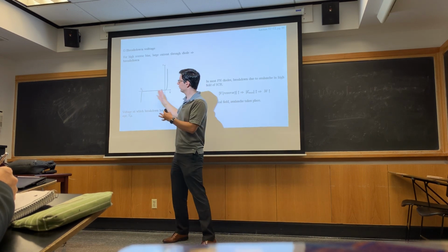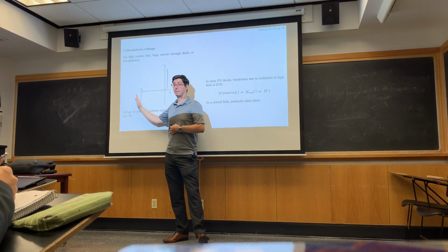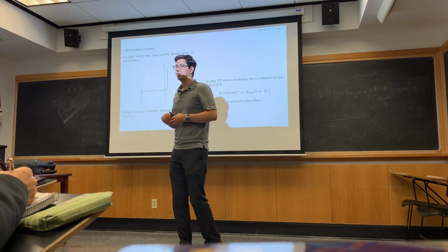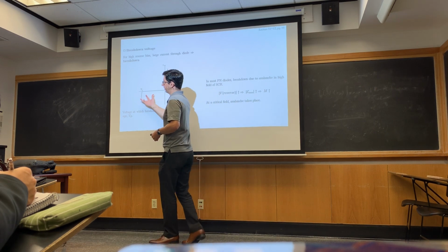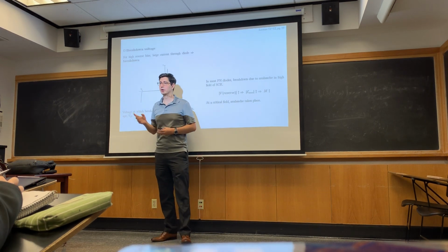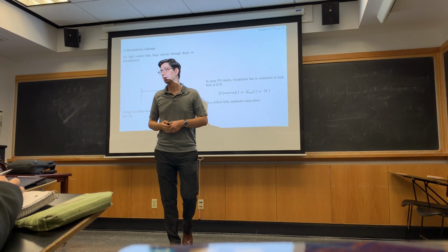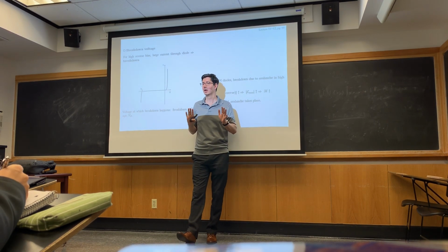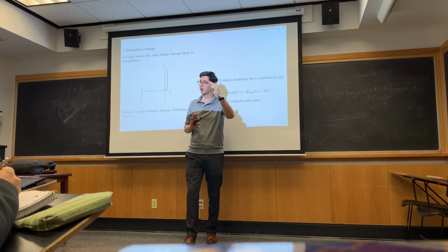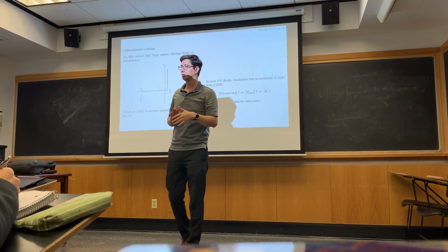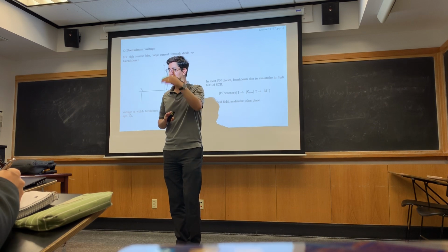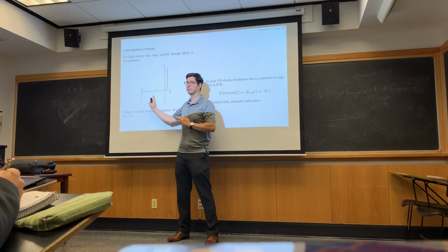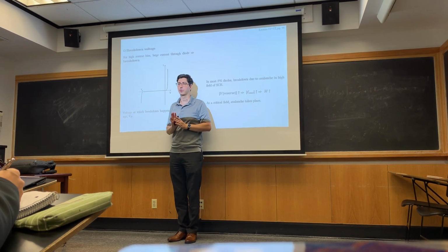So let's say the max voltage I want to apply might be minus 10 volts. If I put, in that case, a 10 ohm resistor in series with this diode, then 10 volts, assuming the diode is fully conductive, then 10 volts divided by 10 ohms gives me 1 amp. So it would keep me from exceeding my max current rating.